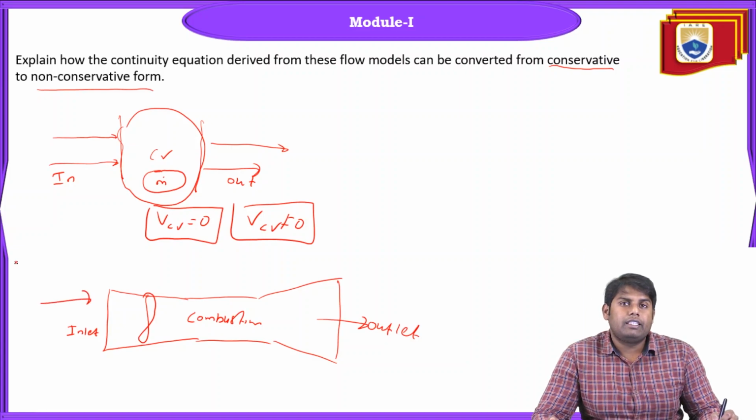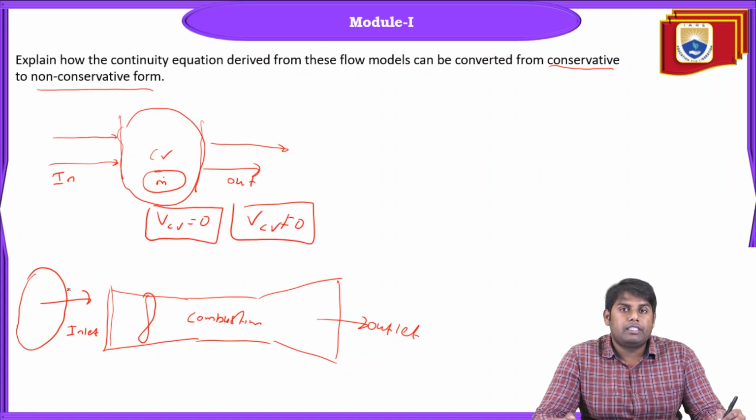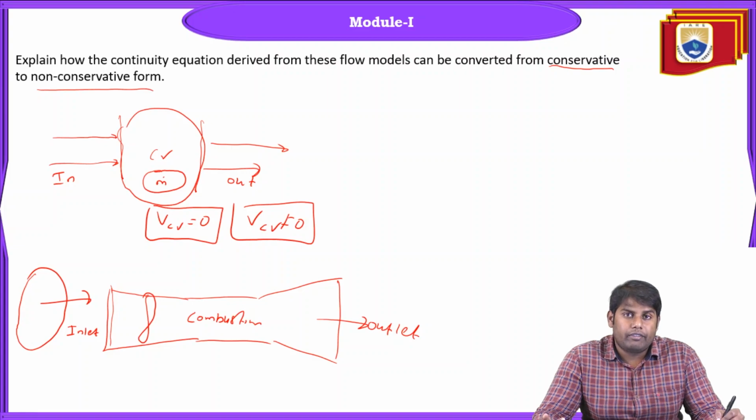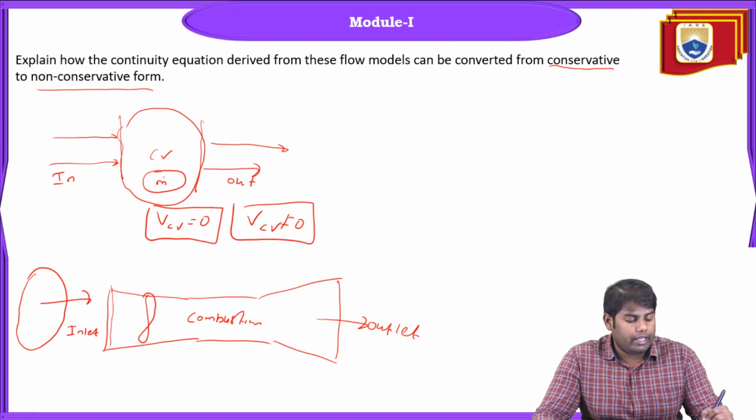So when flow is coming inside, what happens? The flow energy which is present in the ambient is different from when it is coming inside. So there is a change in pressure, or there is a change in velocity. Basically the velocity is reduced. So for the engine, at the inlet, let's say you take a gas turbine engine, turbojet, turbofan, turboprop, you take that engine as a control volume, where at the inlet the velocity is reduced.